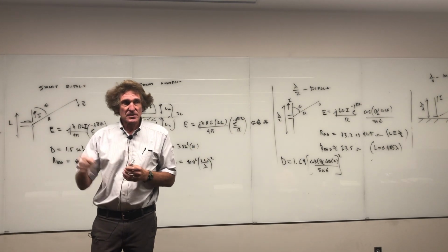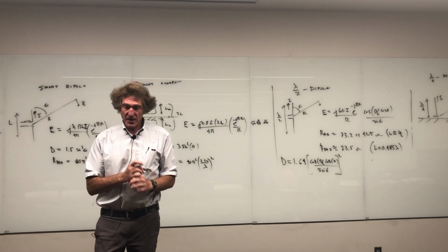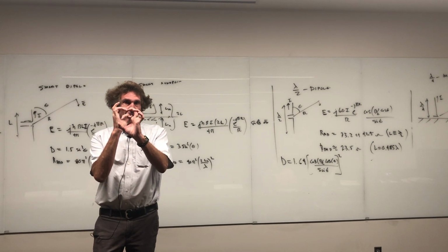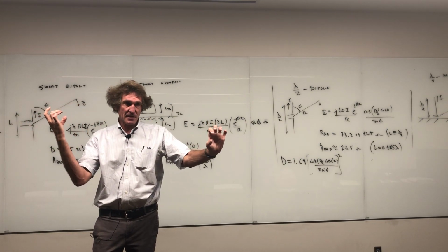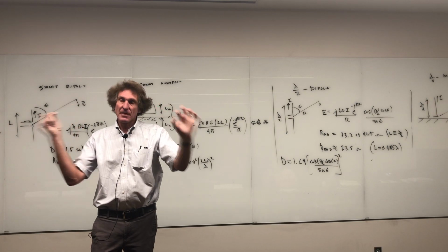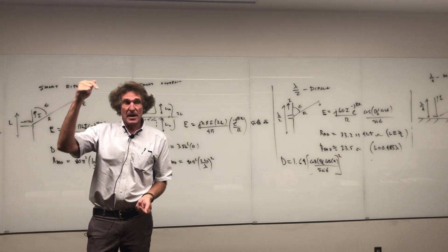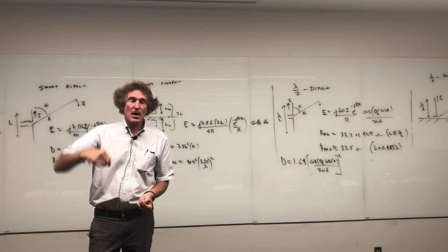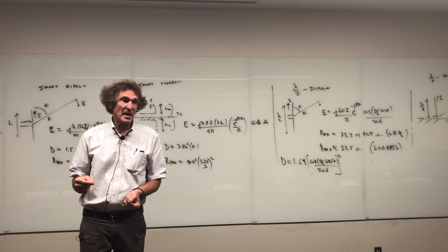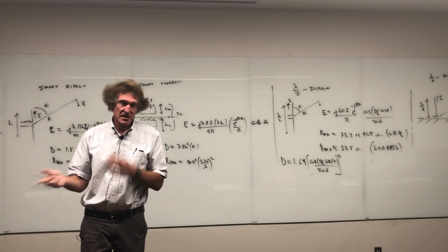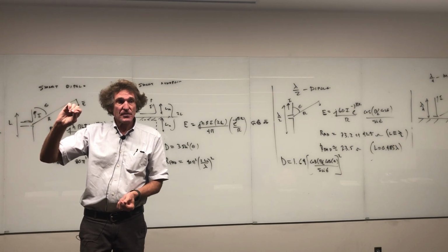So what they do is they make a water resistor. They get thick plastic tubing about that long, and they get about this much of it. It looks like surgical tubing, only a lot thicker, right? And they fill it with water. They put a cork at one end, a cork at the other end, but when they fill it with water, they put copper sulfate in there. What that does is make it pretty conducting, of the order of maybe 30 ohms, 40 ohms, and there are recipes for this, for the amount of water and how much you add. Now you've got a water resistor.